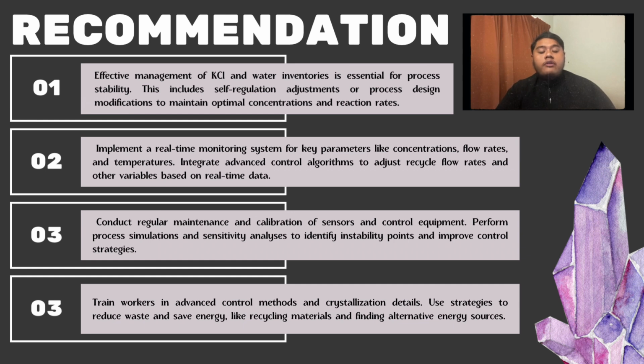Moreover, implementing a real-time monitoring system for key parameters like concentration, flow rates, and temperature can integrate advanced control algorithms to adjust recycle flow rates and other variables based on real-time data. Other than that, we can conduct regular maintenance and calibration of sensors and control equipment by performing process simulation and sensitivity analysis to identify instability points and improve control strategies.